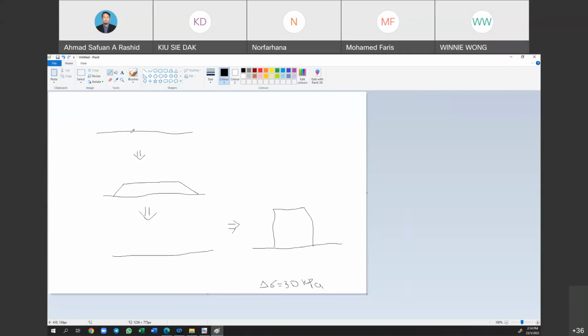As a simple understanding, if this is a ground and we apply something on the top of the ground, we may use the approach of normally consolidated, because before any structure has been developed on the ground, there is no stress history, and also the effective vertical stress is under the same conditions.